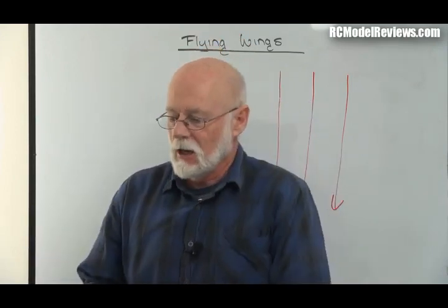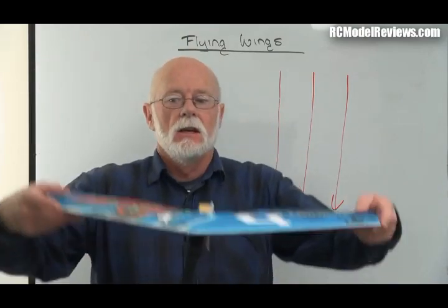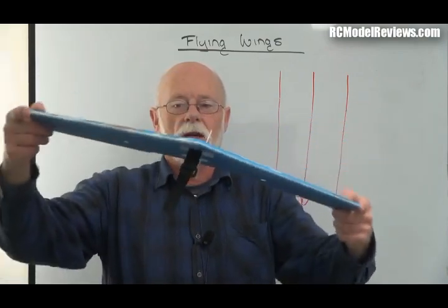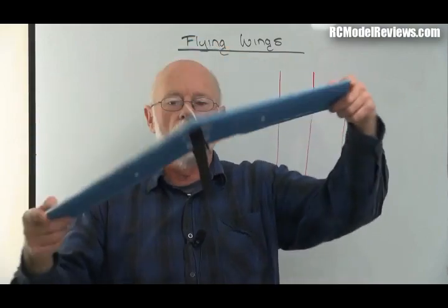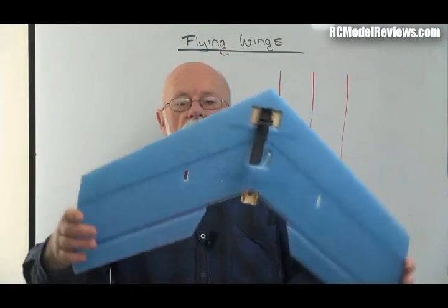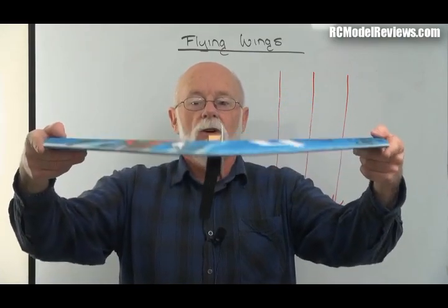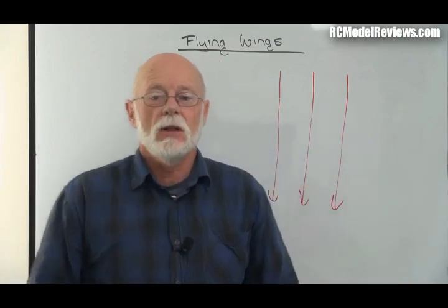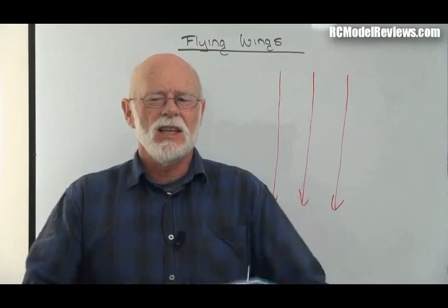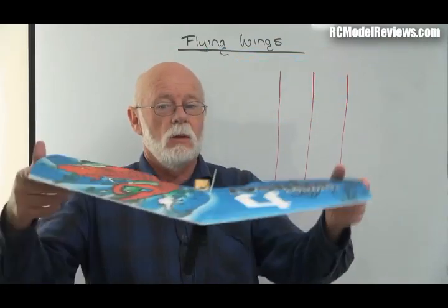And if the dynamics of your flying wing aren't dead right, then what you get is not a yaw and a correction, but a yaw, a roll, and then that gradually dies out like this. So yaw, roll, blah, blah, blah. And that's caused because of the roll-yaw coupling and the self-righting effect, or the self-correcting effect of the sweep on the wing. So it could be really good, but in most cases, because people don't know what they're doing when they design flying wings, you get this. And that's not what we want. But we see it so often with FPV videos of flying wings. They don't groove, they do the wibble wobble.